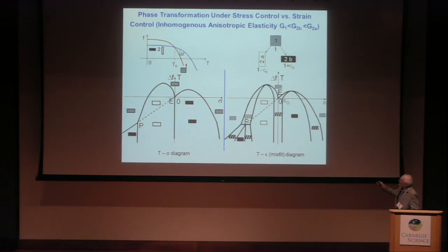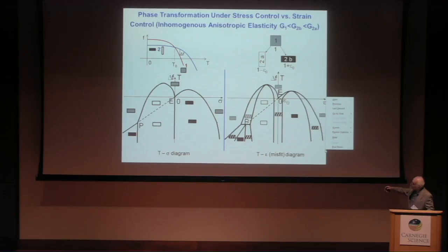Exactly like we have one point which corresponds here, E, which corresponds to the eutectic transition, and one point which corresponds to the eutectic composition. That is what happens at high temperature. But what does this mean? What happens at low temperature? If you come to low temperature, lower than this graph,